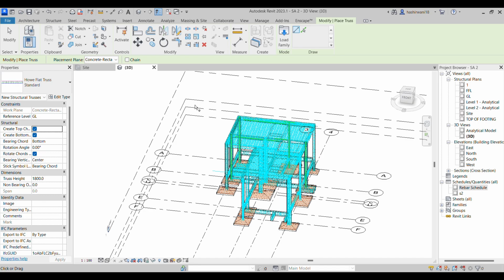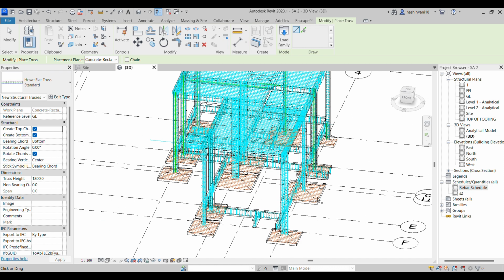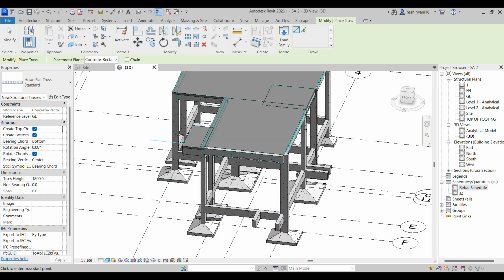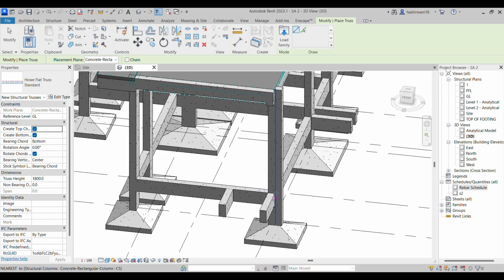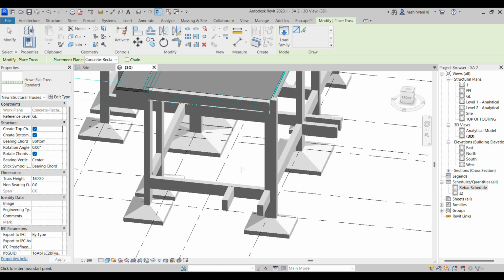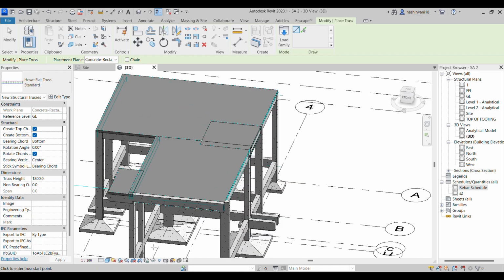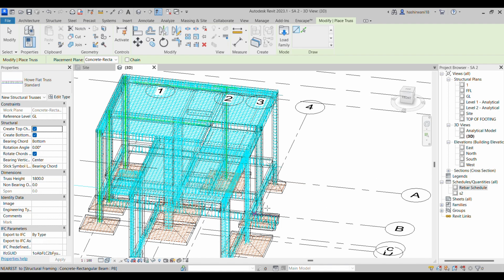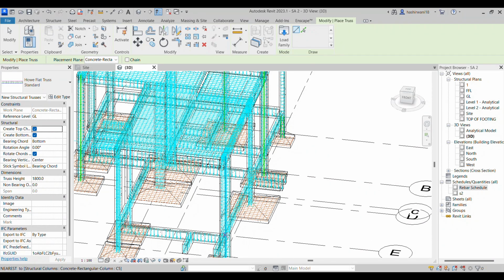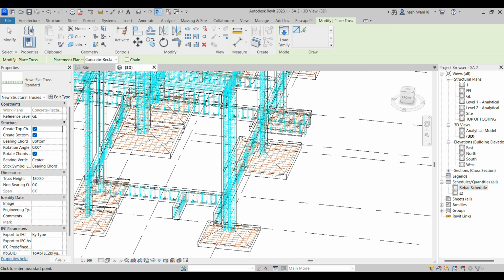So let's start with the first topic, that is our rebar schedules. In the last masterclass, we created some footings. I'll just go back, go to course here and select shaded. Can you see we created some trapezoidal footings, beams, columns, plinth beams, and some area reinforcements, slabs, etc. And if I go to wireframe here, you can see we created some rebars in these structural elements as well. These are color coded according to the diameter of those rebars.